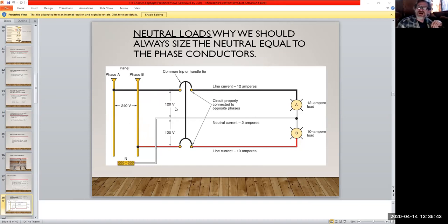That'll usually be on the heavy duty stuff, continuous duty type things like air conditioning or the furnace, where motors are usually involved. You'll run two phases into it, and they call that 240. In that case, you wouldn't see the neutral there, okay? But that's allowable because that runs on both sides of the transformer, so the current path is allowed to be delivered back. But for most devices in your house, you're usually running the black and white or the red and white.